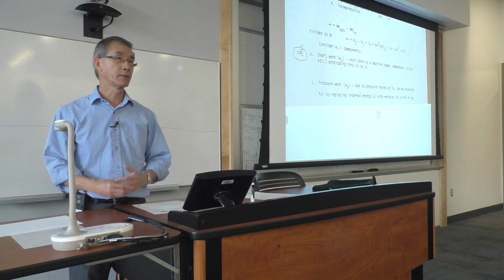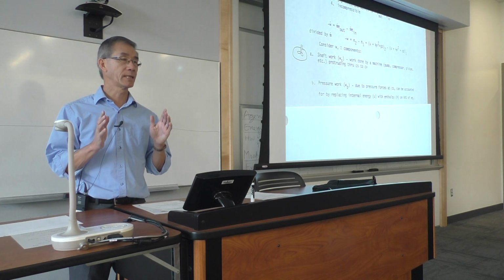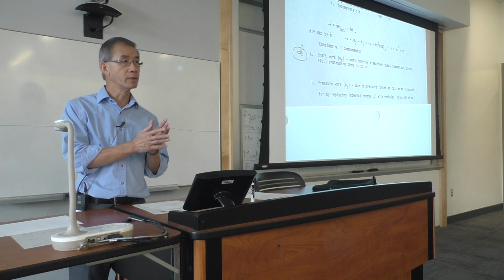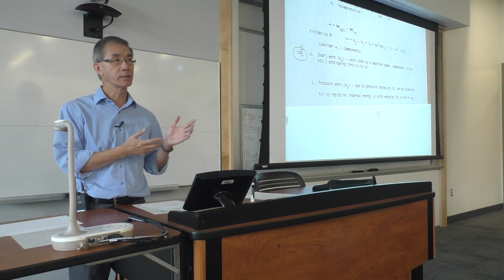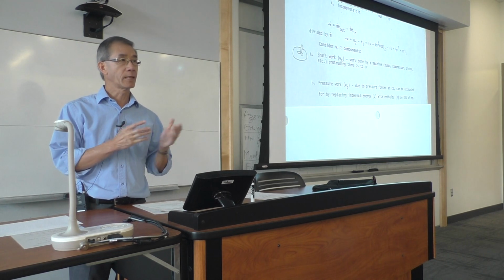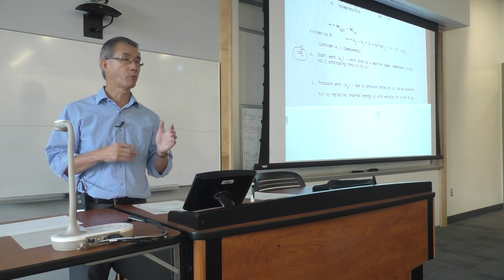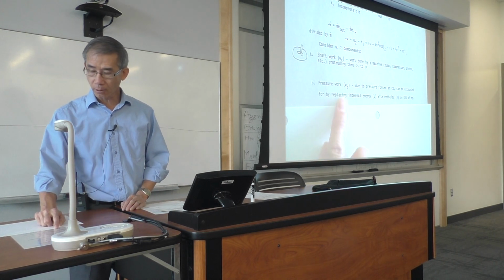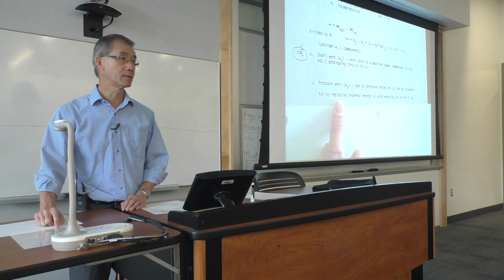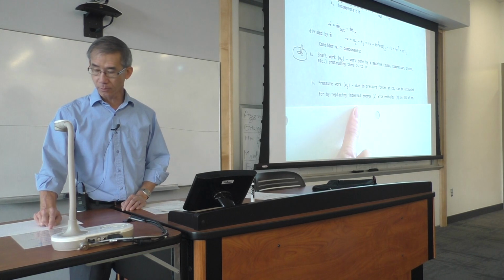And it comes about because now we are not dealing with a fixed mass in the system. We are now dealing with fluid that enters and leaves my control volume. As those fluids interact with my device at the inlet and the exit port, that motion can create work that we call pressure work or flow work. And that can be represented from thermodynamic principle.